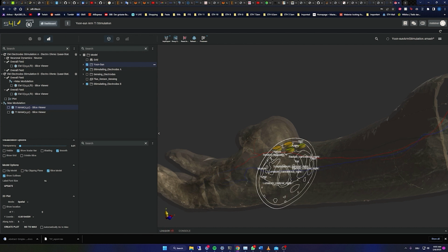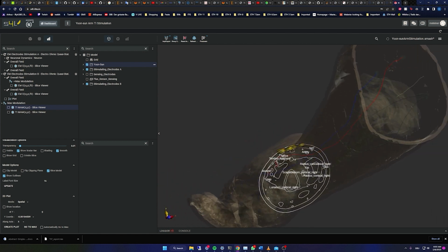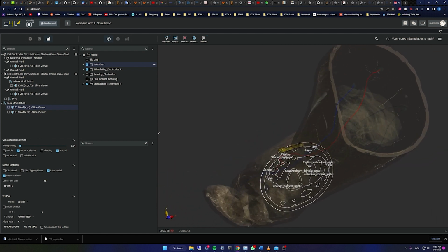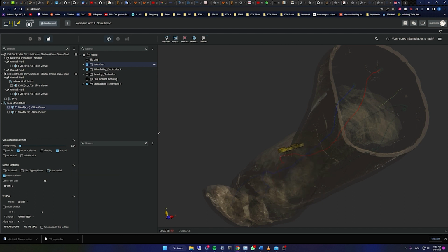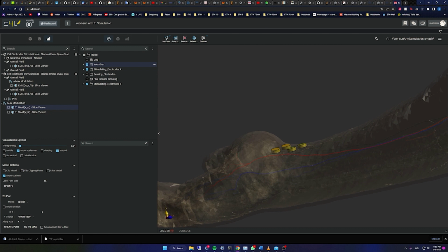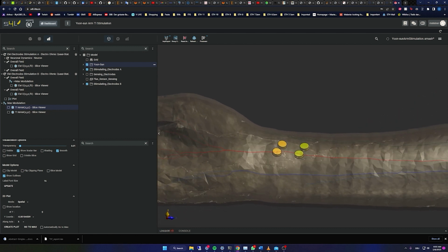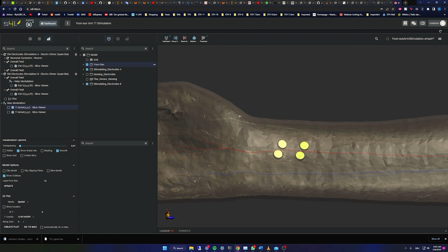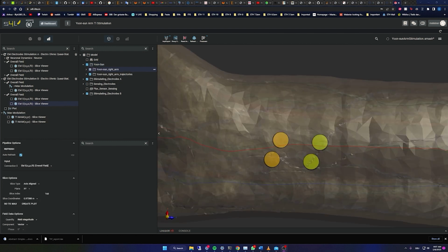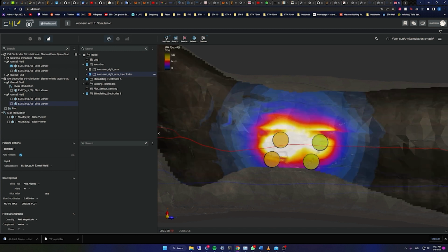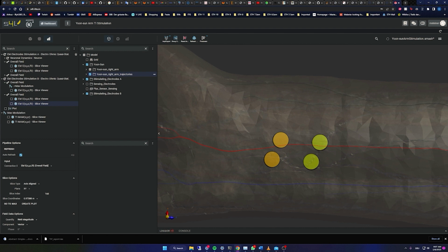To predict the most effective arrangement and optimize the electrode placement, I am placing two sets of electrodes on the forearm of the Yunsun model that is part of the S4L Web Lite offering, and perform electromagnetic exposure simulations for each channel. Built-in advanced post-processing functionality permits to compute the resulting TI exposure, which I can subsequently use as stimulation source in a neuronal dynamic simulation. Here you can see how the induced spiking activity and signal propagation is predicted to result in a measurable surface potential.